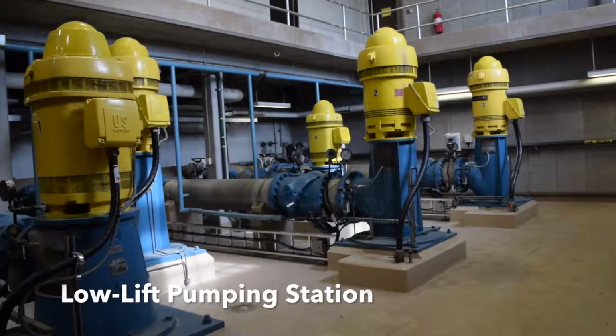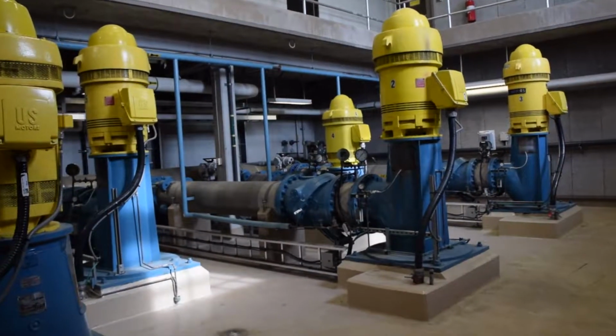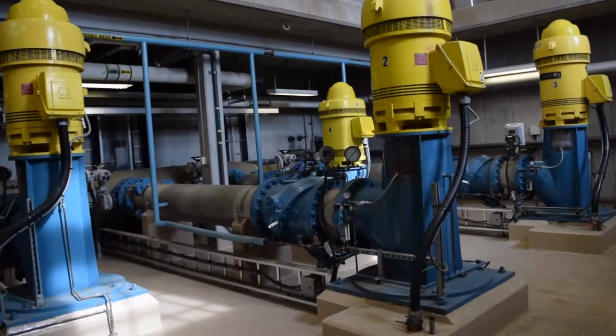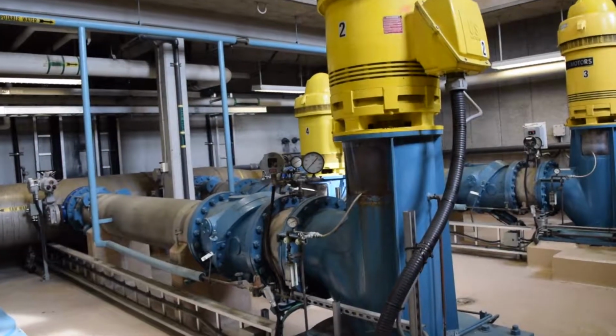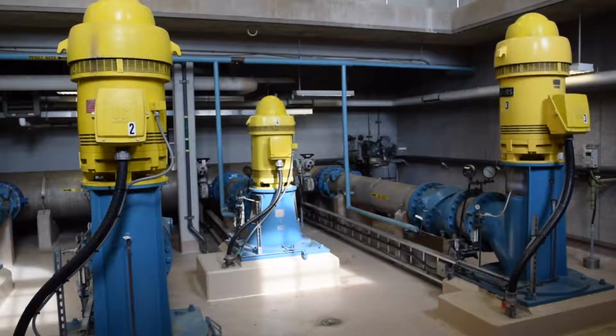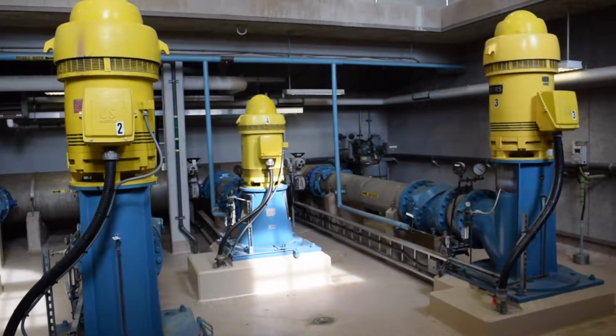Once the water has been screened, it makes its way over to the low-lift suction wells. From the low-lift suction wells, one of the 5 low-lift pumps, which all vary in capacity and rating, will discharge the water at high speeds to a common pipe that then splits off into 2 additional pipes, which feeds each of the 2 flocculation tanks.